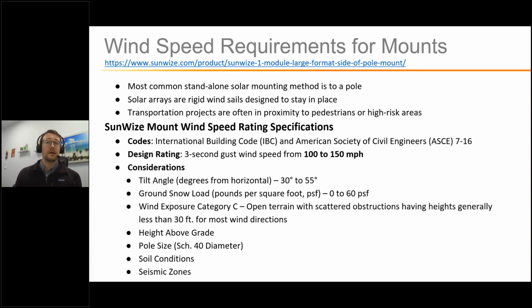The other major consideration is going to be height above grade. The higher you go above ground level, the faster the wind speeds generally are. And then you have the pole size diameter, given generally in Schedule 40. And then you have soil conditions, and beyond that, seismic zone consideration. So many, many things go into determining a valid certification requirement for a mount.